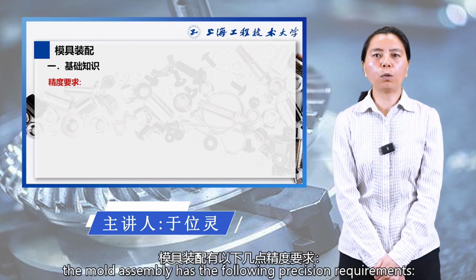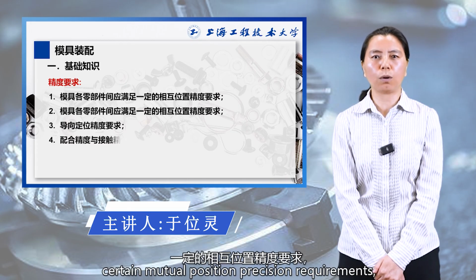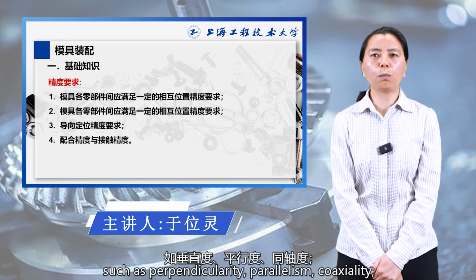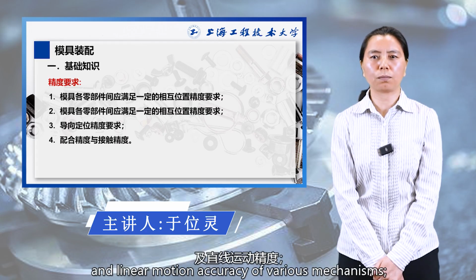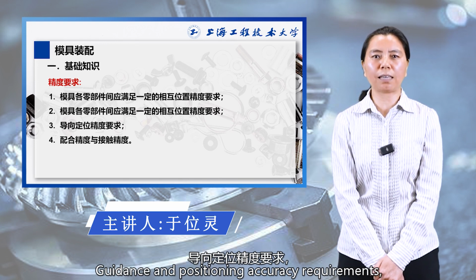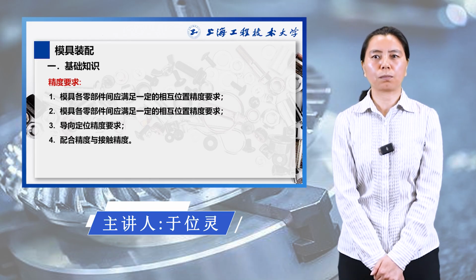the following precision requirements. The parts of the mold should meet certain mutual position precision requirements, such as perpendicularity, parallelism, coaxiality. The moving parts should have relative motion accuracy requirements, such as transmission accuracy, rotary motion accuracy, and linear motion accuracy of various mechanisms.